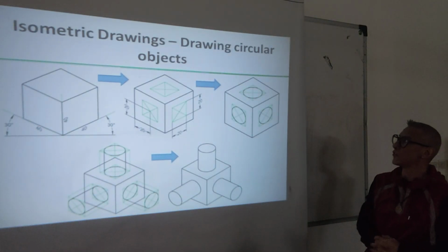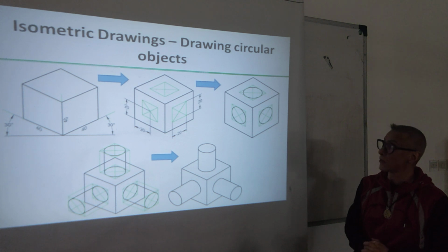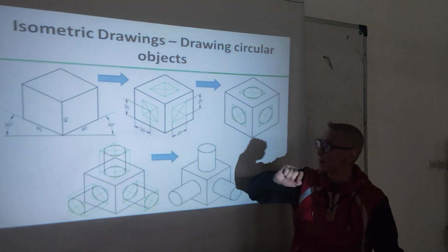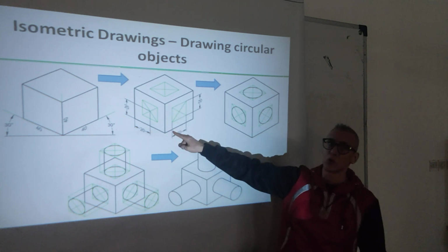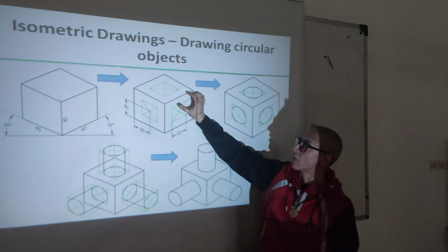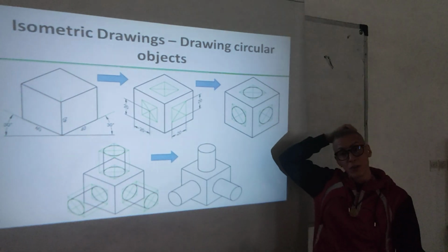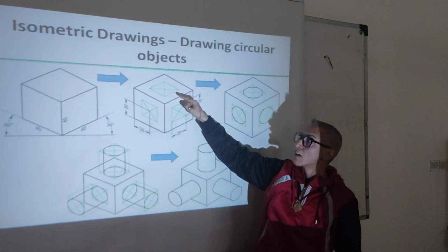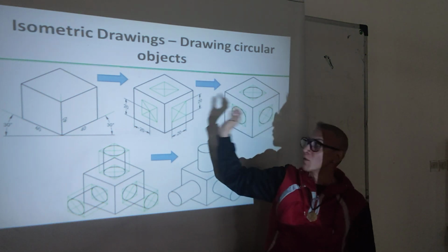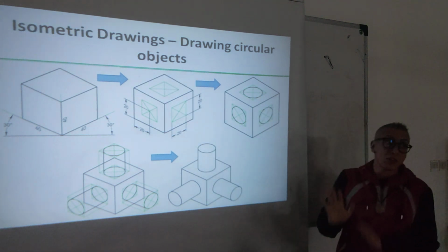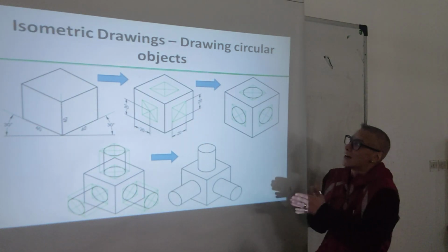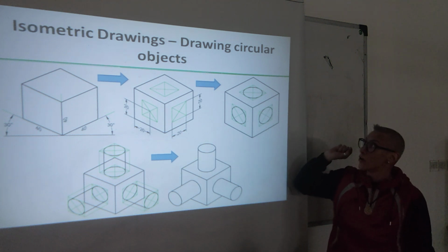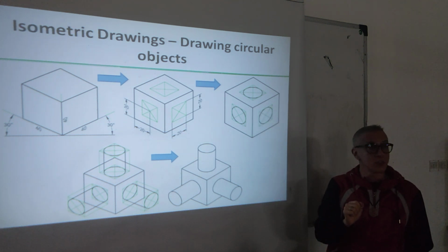Okay. Now, this is an example with circular objects again. So, at isometric, 30 degree, 30 degree. Then, before you draw any circles, the squares are located. The location of the squares, exactly. Now, in isometric drawing, remember, everything is in its correct measurement. So, if this is in the middle, in reality, it will be in the middle in the drawing. So these spaces are all the same, because it's isometric, okay? Not a perspective drawing. So you identify the location of the squares, you follow the steps that need to be followed, okay? Then, using the compass, you will draw each circle.